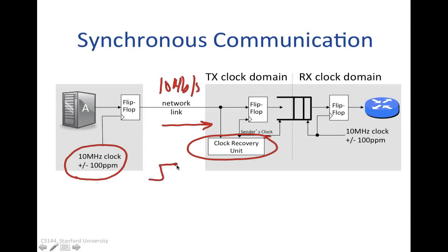So it's going to look at the bits and say, aha, if I can actually detect when there's a transition, then I can determine what the frequency was and where one bit starts and another bit ends. So it's able to recover this. While the bit pattern could be anything, if there's a strong enough component in the spectrum from the sender's clock of what its frequency was, then the receiver will find it and use it to sample the bits.